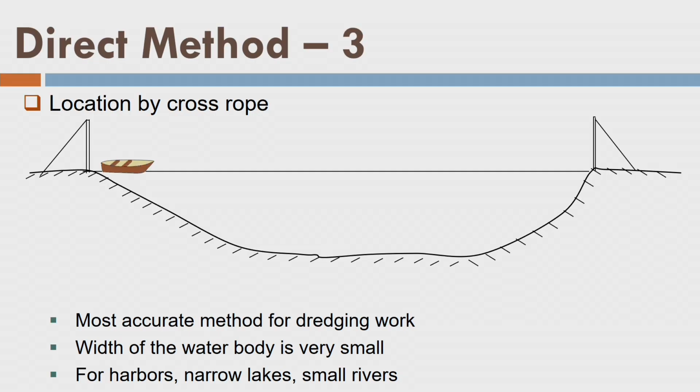That means it's like a float line, although the float line is needed when we want our reference line or our range line or our survey line to float over the water. So right now the requirement is not like that. Fine. Now we are stretching the rope, and this is my water level here. Fine. So the boat is there also, right? Okay, so we have stretched our, let's say, float line across to this point and this point.